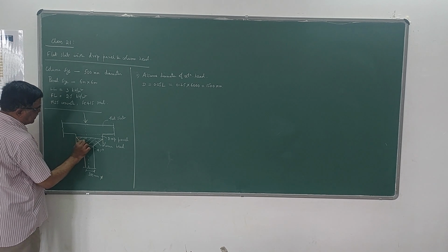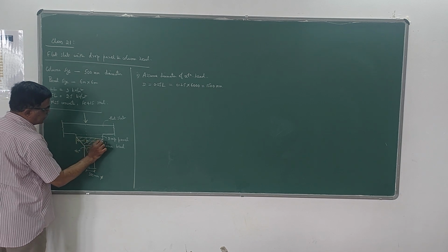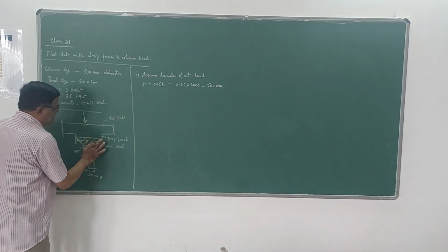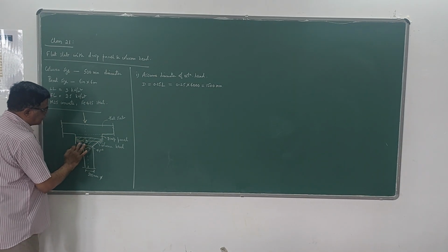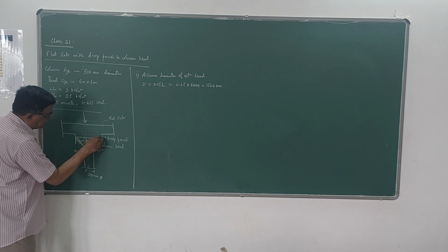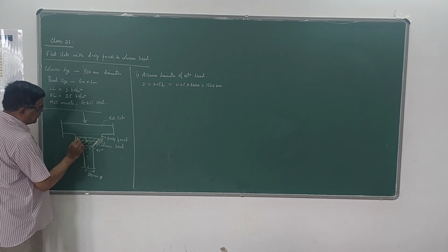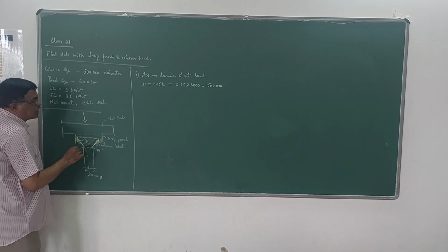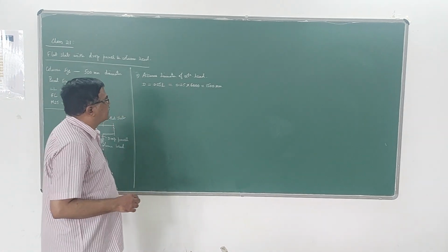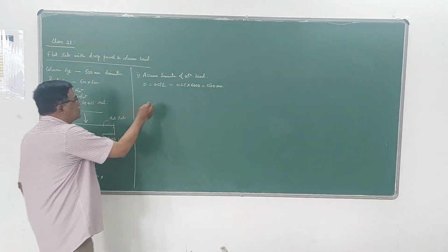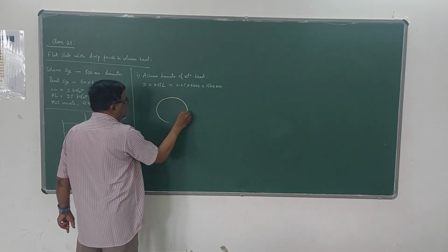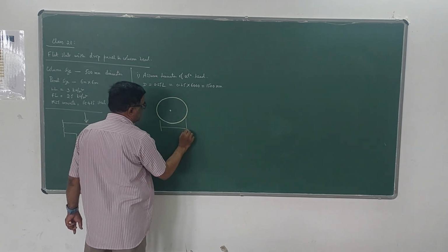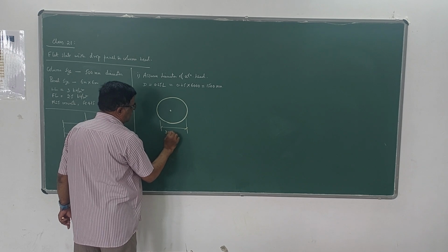From here to here. Of course, in this sketch you can take it somewhere from here. So this is your diameter from here to here. You can assume that as 0.25 times the panel size. That means in plan, the column head looks like this. This is the diameter, 1,500.